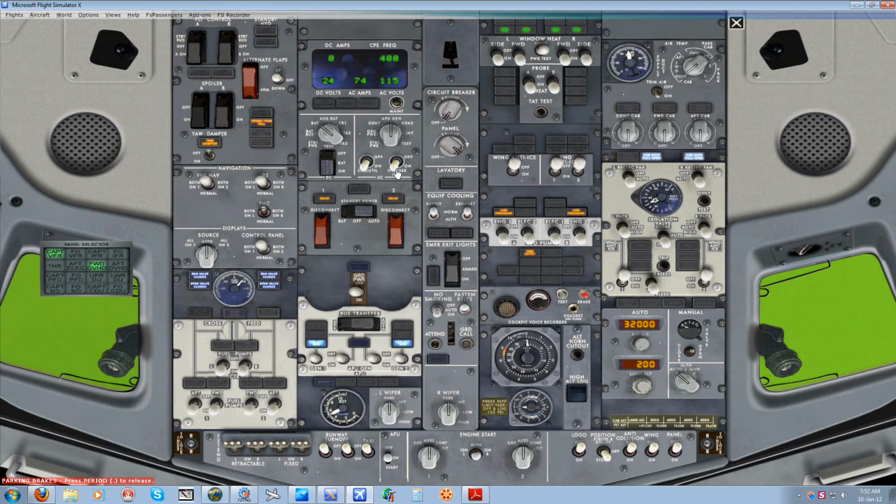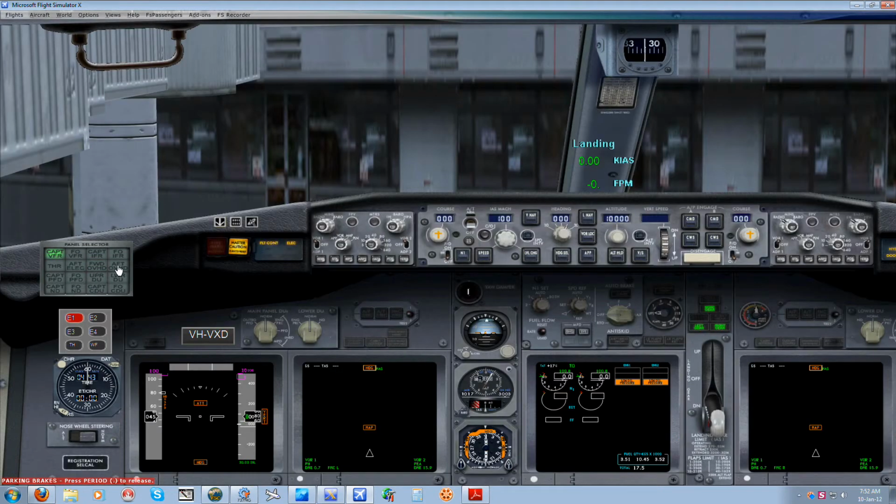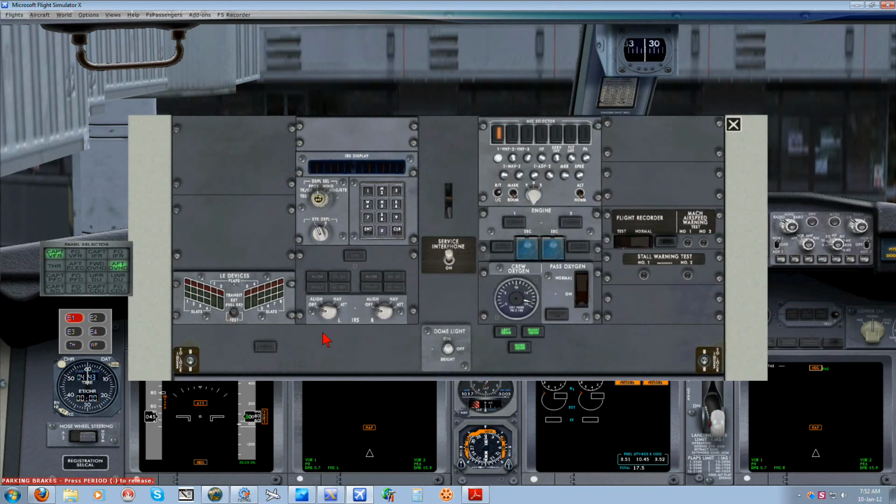So it's important that you get those on, otherwise there'll be no power to the passenger cabin or the crew galleys. Okay, once we've done that, that's pretty much it for the overhead. We'll come back and program a few more things up here and turn a few more things on after. But we can close that down now, and we open up our aft overhead.